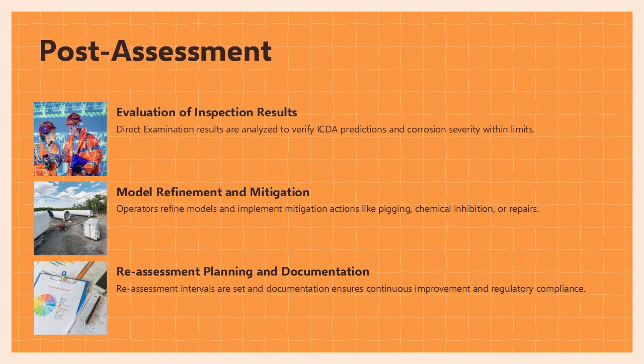These may include enhanced pigging programs, chemical inhibition, operational changes, or repairs to damaged sections. Post-assessment also establishes reassessment intervals based on observed corrosion rates, confidence in the ICDA process, and regulatory requirements. Documentation is critical, as this step provides evidence of due diligence and continuous improvement. A well-executed post-assessment ensures that ICDA remains a living process, adapting to new data and changing operating conditions while maintaining pipeline integrity over time.